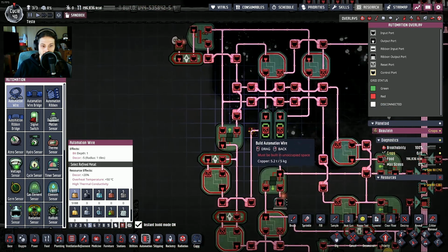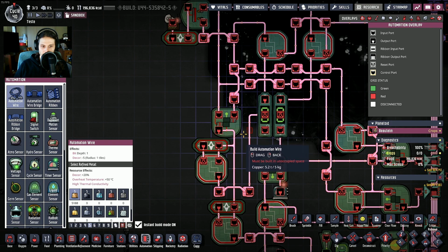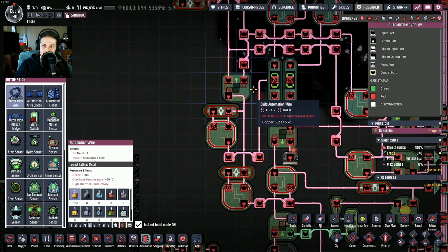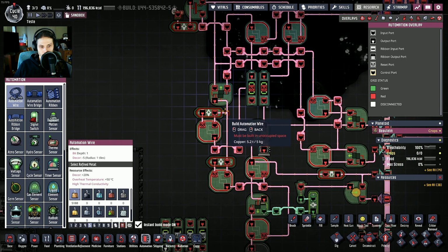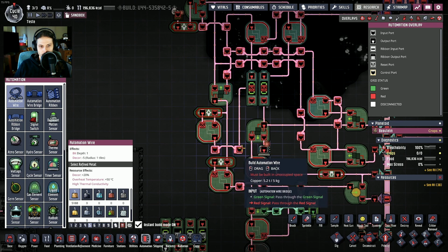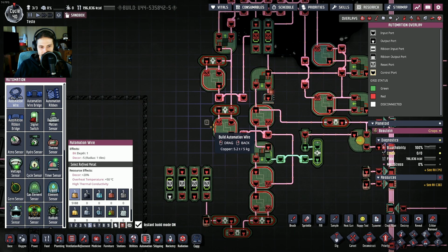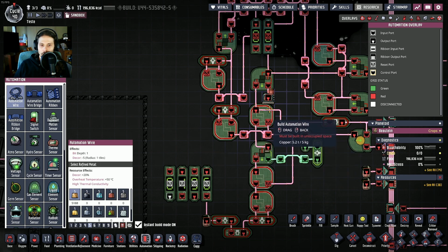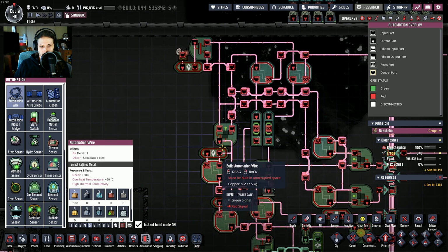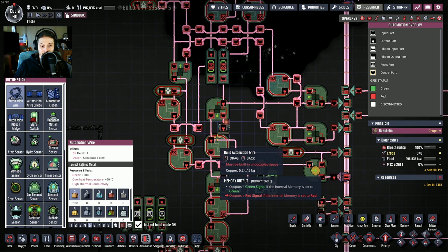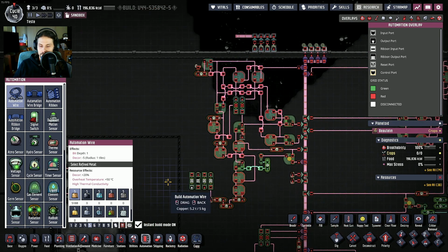And then they are also going to travel through another AND gate over here. This AND gate is the reset or turn off AND gate for the entire encoder. Pretty much it's going to be twofold. It's going to generate a pulse over here and generate a pulse over here. This pulse will reset the counter, and this pulse will travel through this wire, resetting the memory toggle for the waiting signal and the memory toggle for the turn on and off signal. And yeah, once this signal has reached over here, the entire system has been reset and turned everything back to 0. All the things are shut off, and everything is cool.